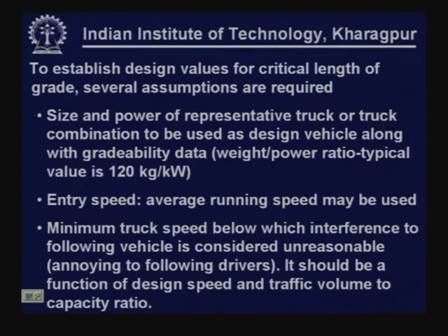A typical value may be 120 kg per kilowatt. So, we have to specify the size and power of the representative truck, and the gradability data, particularly weight power ratio, becomes critical.